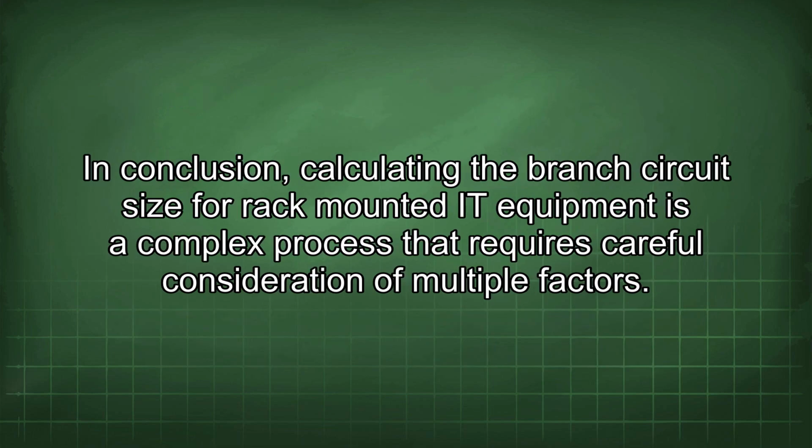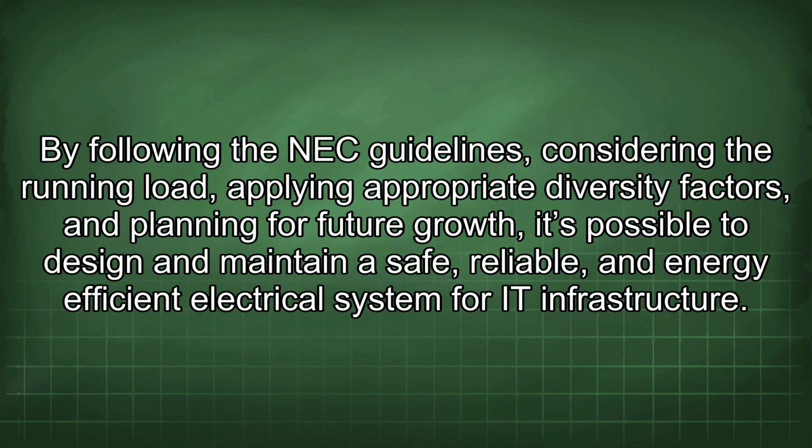In conclusion, calculating the branch circuit size for rack-mounted IT equipment is a complex process that requires careful consideration of multiple factors. By following the NEC guidelines, considering the running load, applying appropriate diversity factors, and planning for future growth, it's possible to design and maintain a safe, reliable, and energy-efficient electrical system for IT infrastructure.